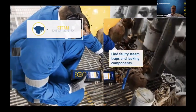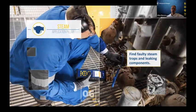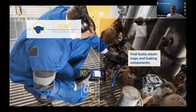Just like a valve, we have steam traps. Steam traps are really just a valve with an IQ of 1. I like to refer to a steam trap as a toilet. Its job is to remove waste so that our boiler feed water can remain pure. So a steam trap's job is to sit there and collect condensate and then purge it from the system. Well, when a steam trap fails open, I'm going to have turbulence across the steam trap. When a steam trap has failed in the blocked position, I'll have no turbulence across it.